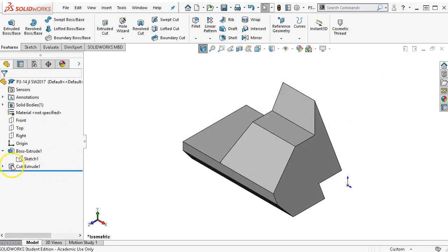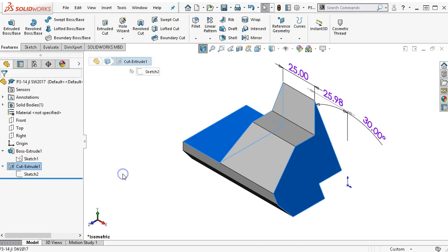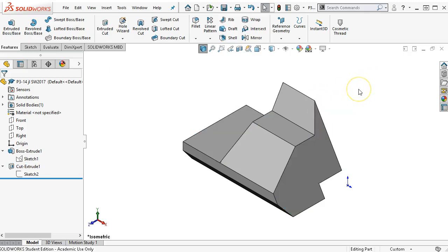And then we'll go back in, and I think I should just be able to double click, and we're at 25.98, which if we go in and take the tangent of 30 degrees and multiply it by the 45 millimeter height, we get 25.98. So if our tolerance is plus or minus a millimeter, that's still an issue, but it's not as bad. So when we get those anomalies, we're going to stop and check and figure out what's going on.